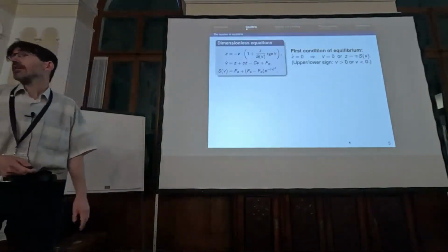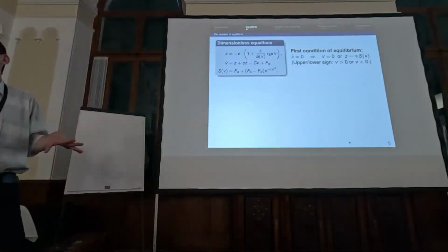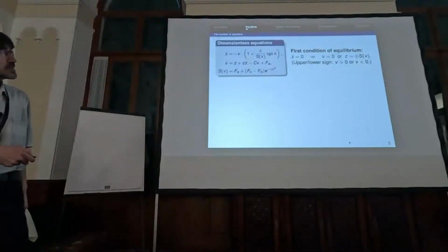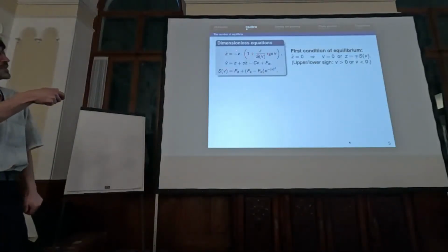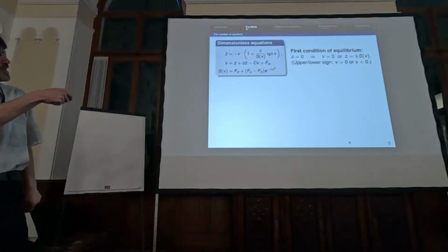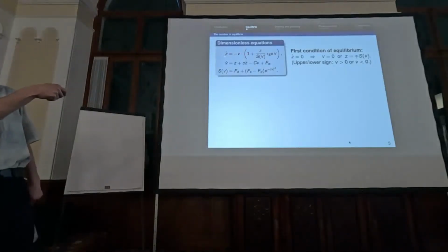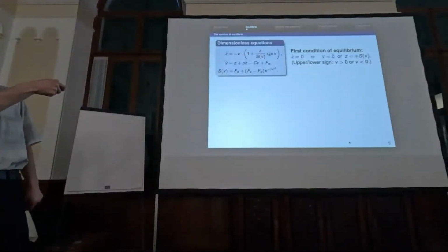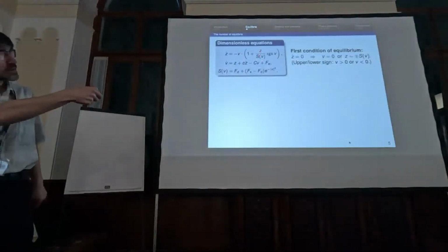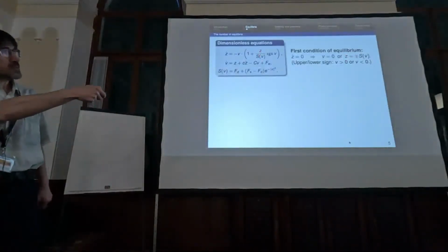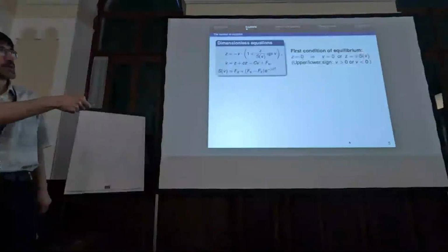In the first step of the analysis, we wanted to find the equilibria of the system. And first, we considered the differential equation of the bristle deformation. From this, you can see that if z dot is 0, then either the velocity is 0, or we obtain a condition for the bristle deformation that is given by the Stribeck characteristic.